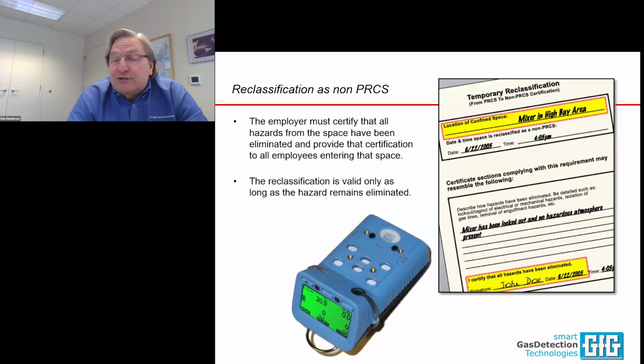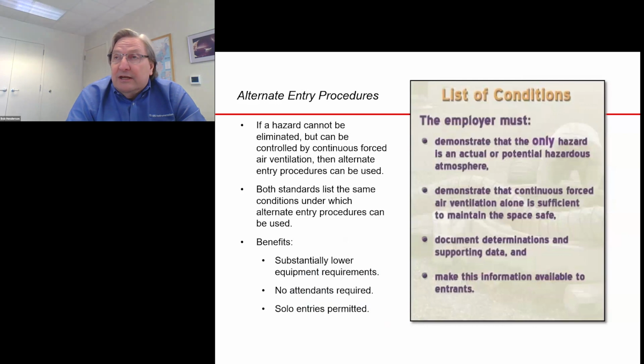The employer must certify that the reclassified confined space meets these criteria. So you're leaving a paper trail of what you have done. You've certified that all the hazards have been eliminated. This is a signed document. You're going to retain it for your records and take reclassification very seriously. It is a permit required confined space until, through reclassification, it isn't. So make sure you follow the rules for reclassification.